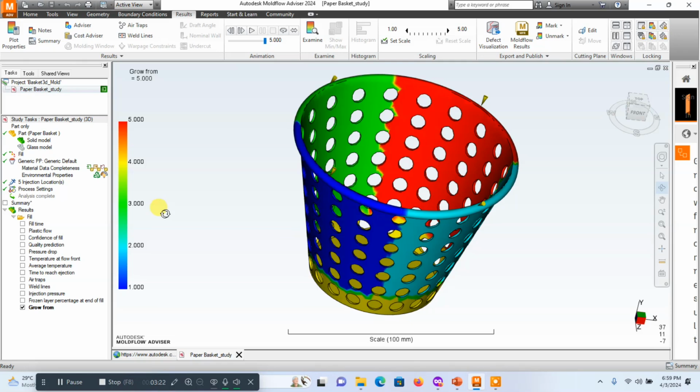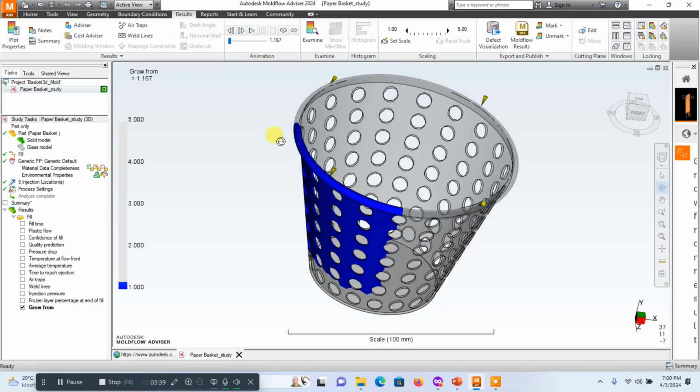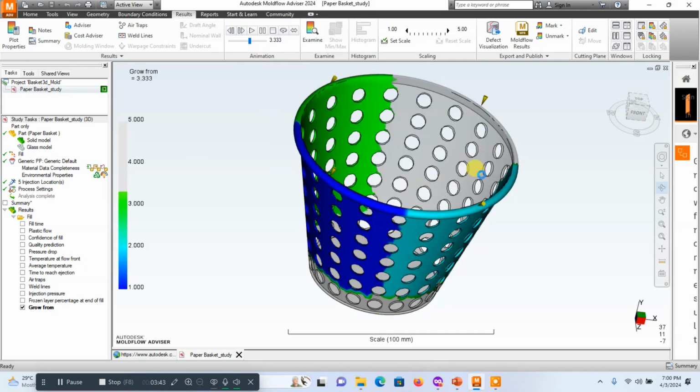Now, let's take a brief look at problems and possible resolutions. For instance, if you have unbalanced flow patterns, which can be caused by one, polymer filling more quickly from one gate, two, polymer from both gates trying to fill at the same time, or three, a weld or mold line in a very sensitive area.